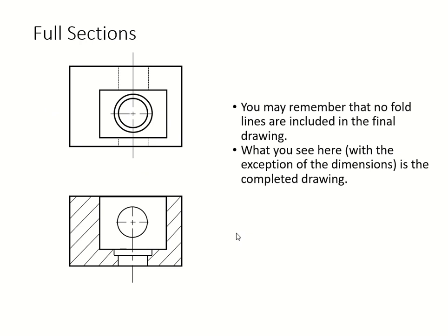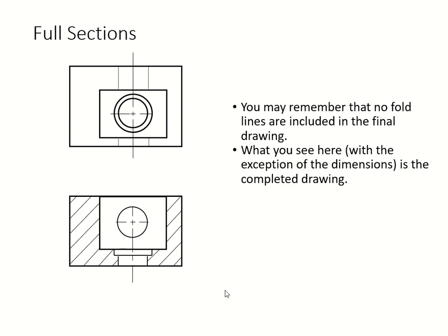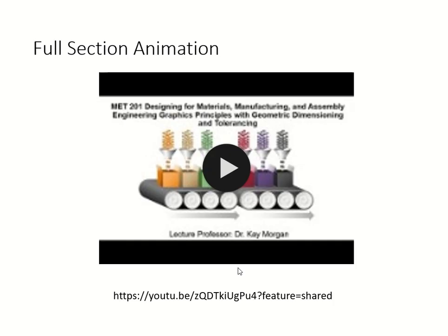Okay, and of course we don't use our full line. This is our full line anymore. We will get rid of it after you complete your drawing, so erase it, and here is our completed full section view drawing.